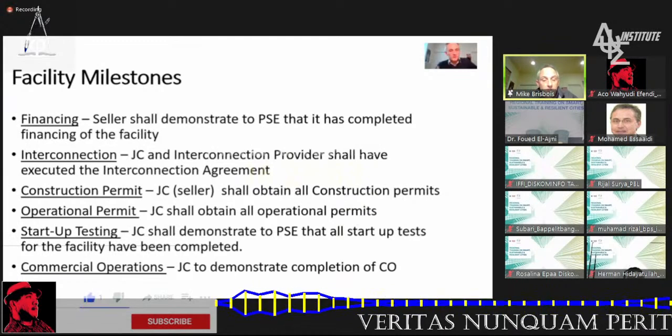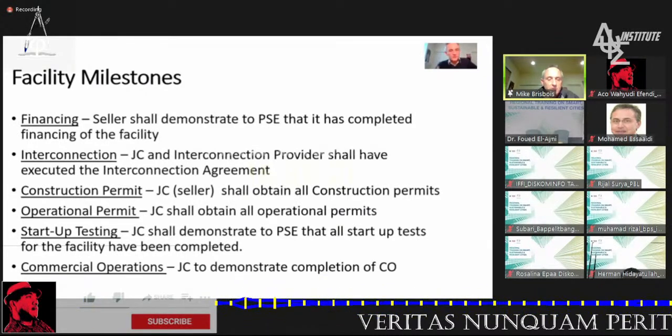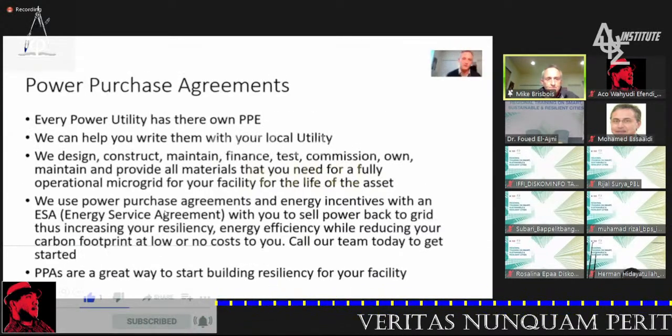Make sure everything is good. We don't want any arcing. We need that wave to stay in sync when it changes back. So is it a make-before-break situation? Is it the islanding switch, where the whole thing is totally in island mode, operating on the facility by itself, or do you actually take in solar and utility power at the same time? So a lot of questions there.